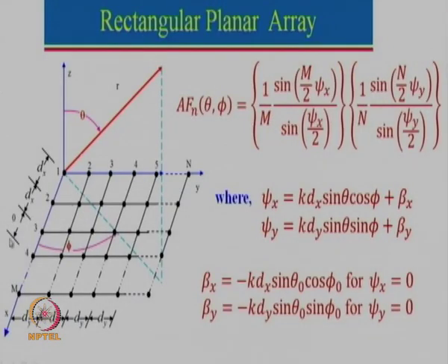it will still have no problem of grating lobe, but actually speaking that is true only for the x axis and y axis. Let us see what happens along the diagonal axis here. If I take this as, let us say, 0.7 lambda, and this I take as 0.7, the diagonal length will be square root 2 times this, which is almost coming to lambda. So we may satisfy the condition along the x axis or y axis, but along 45 degrees I will have a problem of grating lobe. So generally speaking, we do not try to take more than 0.7 for this spacing here,